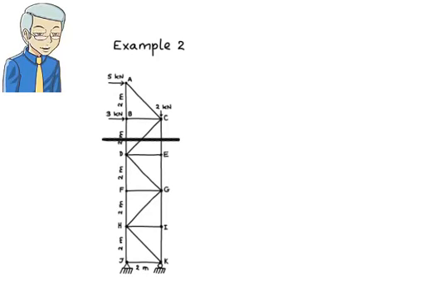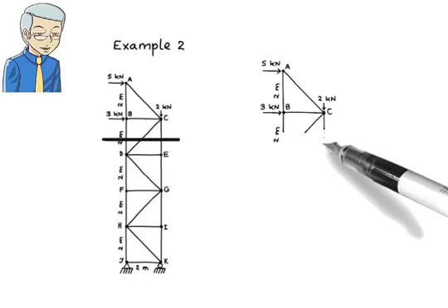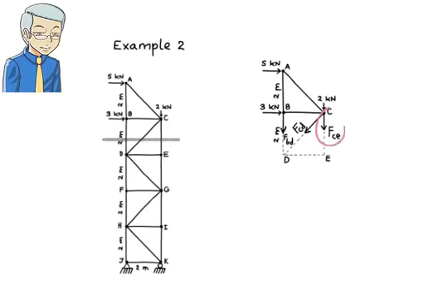The free body diagram for the top substructure looks like this. The diagram shows three unknown forces, FCE, FCD, FBD. Since we can write three equilibrium equations, we can calculate all three forces, but we're interested in calculating FCE only. Therefore, it makes sense to simplify the solution by using one equation only. The equation of interest must only have FCE as an unknown. No other variable should appear in the equation, otherwise we would not be able to use it to solve directly for FCE.